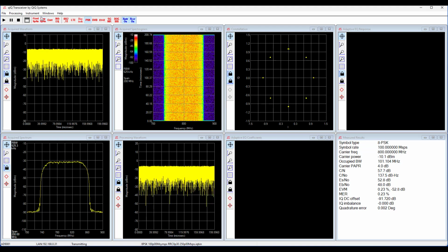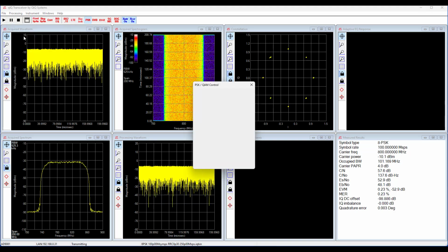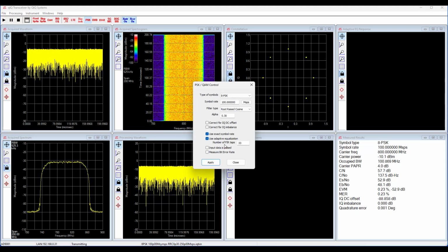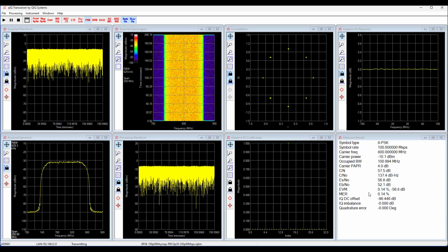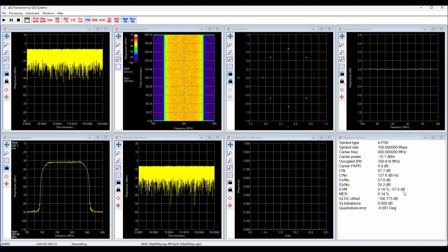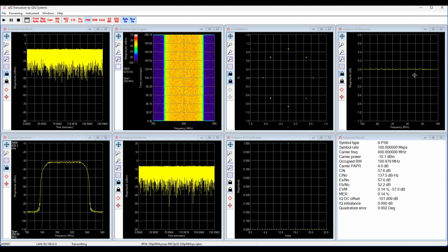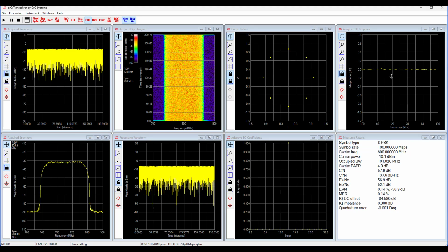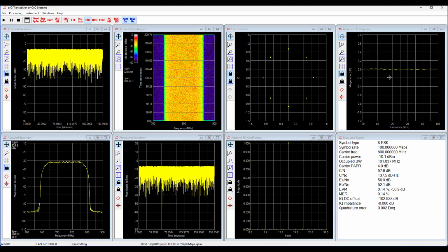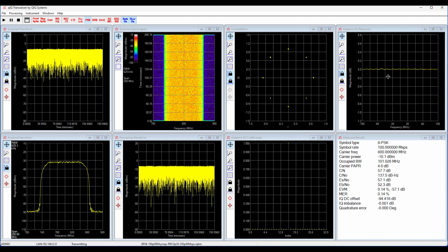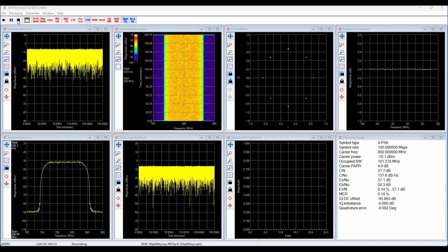Then if we want to, we could actually go in here and add on to the signal processing. We could add on some additional adaptive equalization just to do the final cleanups on here. And you can see if we do that, then the EVM gets very close to the carrier to noise ratio. But the response shows there's really not that much for the adaptive equalization to do at this point. Almost everything's being done by those coefficients that come from the chirp equalization that we did.